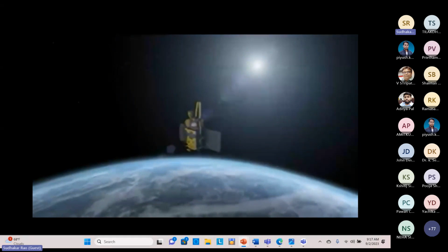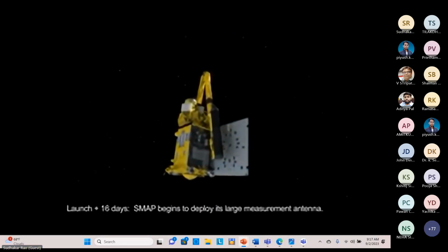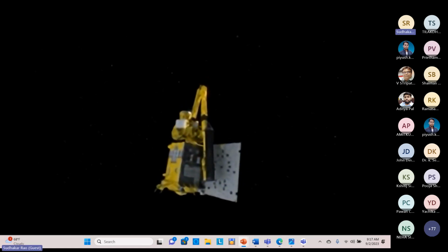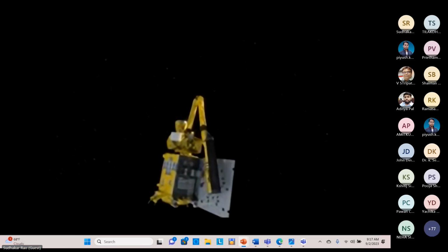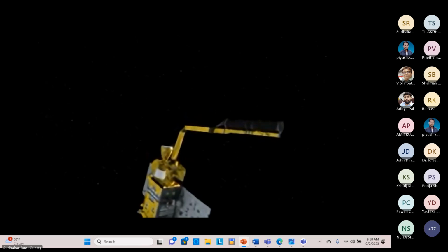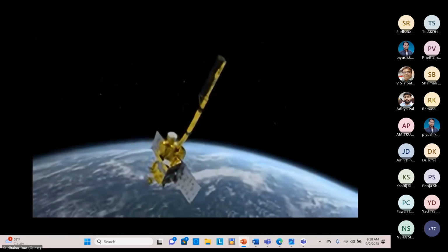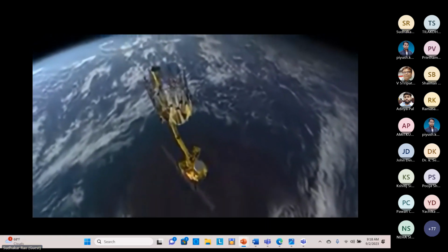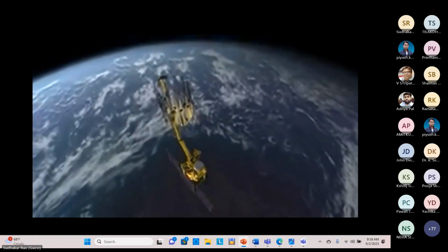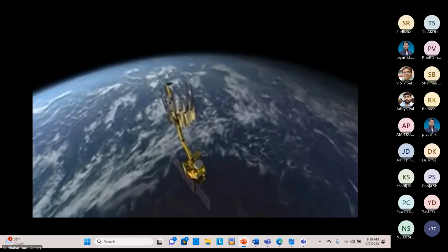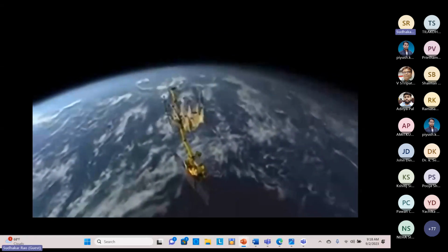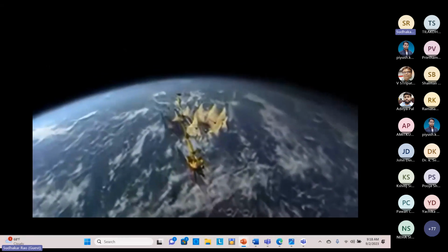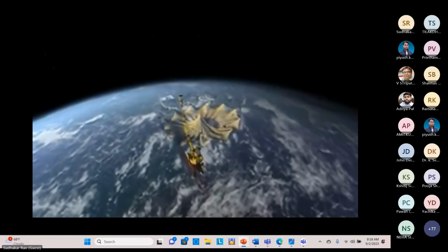Once in orbit, the first thing is to deploy the solar panels. Now you see the deployment of the mesh reflectors. It has to be done very slowly. And then the black cylinder deploys like an umbrella. Since it's in a polar orbit, it rotates at about 35 RPM, conical area, so it provides a swath of about 1,000 kilometers on the ground.